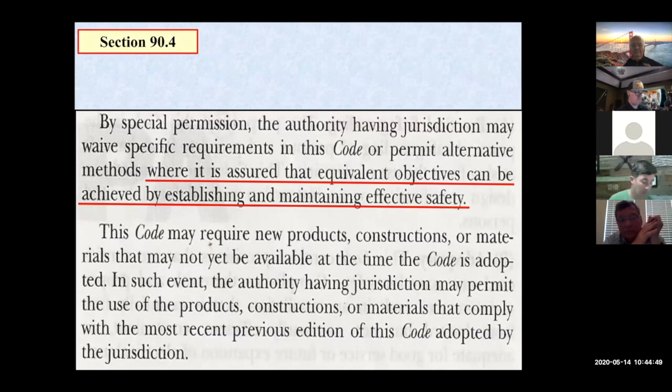I've also been made aware that the IRC that a lot of people use, I'm particularly not real familiar with that, but it adopted the 2014 National Electrical Code. And I've had builders say, well, I build under the IRC and the 2015 IRC. Well, that's fine, except that's the 2014 code. I mean, that would be today. So you have to kind of learn how to deal with that. A lot of times you say, well, I want to bring it up to code. Well, that may or may not be something that you can back up with good reasoning.